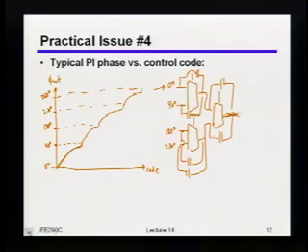Reduce the LO feedthrough. Okay, that's one answer. You could try to reduce the LO feedthrough. Unfortunately, that's actually pretty tricky. I mean, it's possible, but there's actually a more direct way of doing it. If you had dummy caps or something. You're kind of going the right way. You could actually do something like that. That would kind of work. But there's one very simple structural fix that, at least conceptually, doesn't require any extra hardware. Maybe switch the order of the phase? Maybe, although I think that's still a little bit tricky.